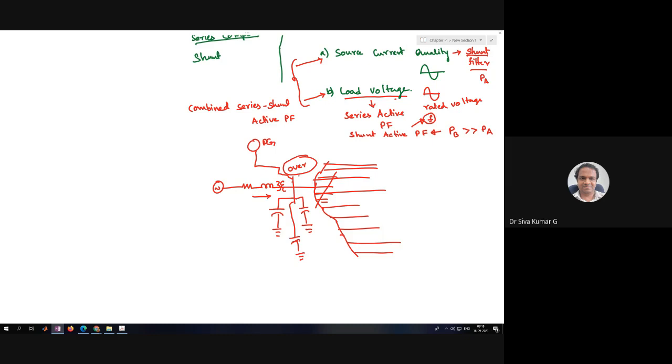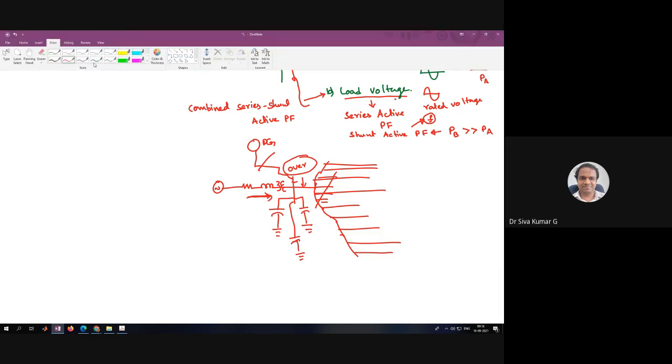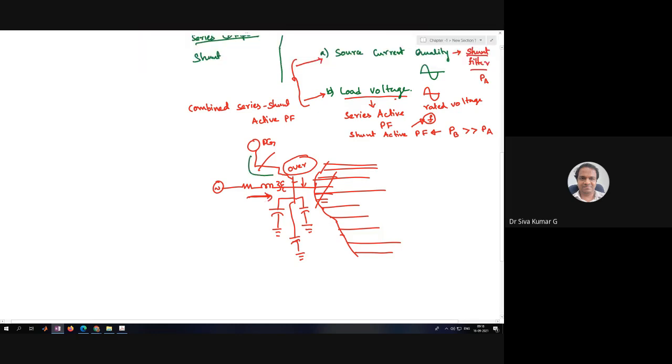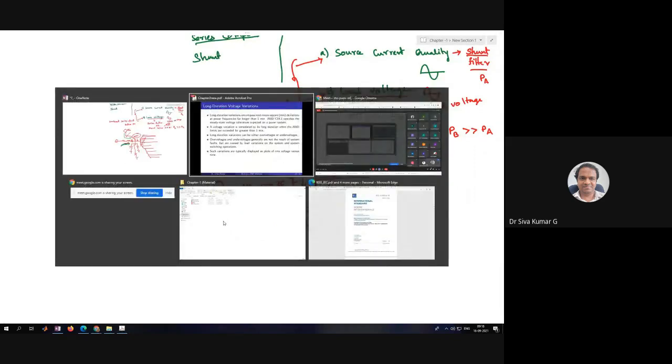Okay, if you have a DG connection, and suddenly the DG gets isolated, in that case also this bus voltage is going to go down, because a huge amount of power is going to transfer through the main line. If you have a DG, then the power sharing is done between the two DGs and the source also. If you don't have the DG, then most of the load is going to be shared by this source only. Then we will be having the under voltage. Okay, are you getting it? It is just an understanding of how the power is shared.